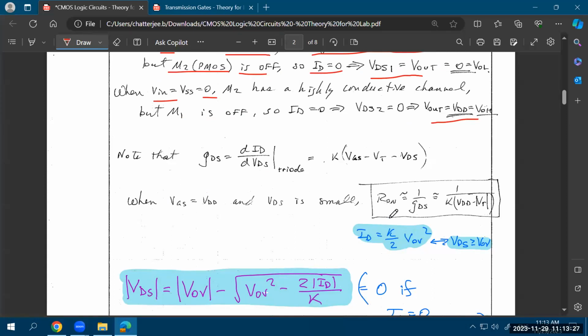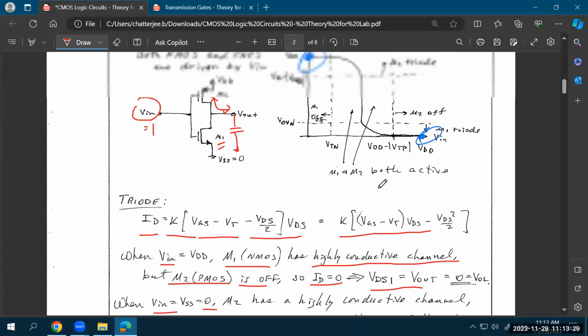Now, what is the resistance? As we were saying, if the devices are off, you have an infinite resistance because you can assume that it's an open circuit. But when the device is on, ideally it should have been a short circuit, but in practice it is not. In practice, you have some amount of on resistance, and that you can calculate from this equation itself,